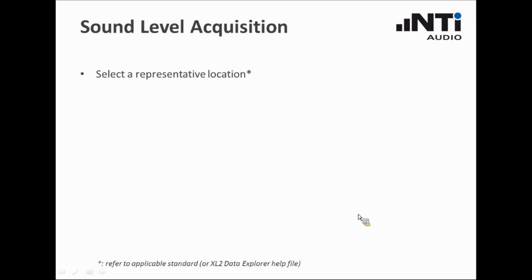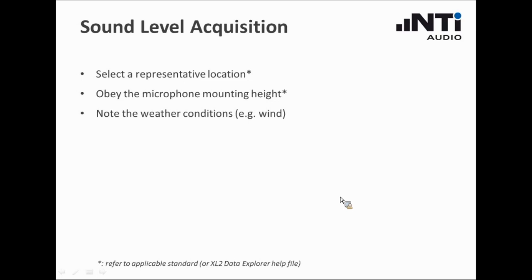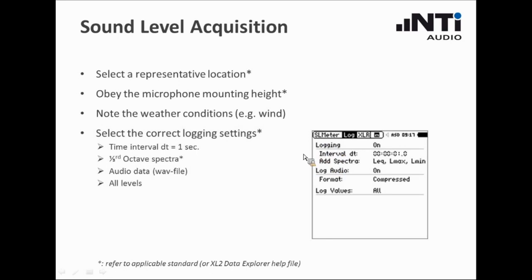When we talk about the acquisition of this environmental noise, we start, of course, with the measurement of that LAeq. We have to look for a representative location. We have to make sure that the microphone is positioned at the correct height and in the correct position. We have to note the weather conditions, especially the wind, because it may play a major role in the result of the measured LAeq. And then we have to prepare our test instrument correctly.